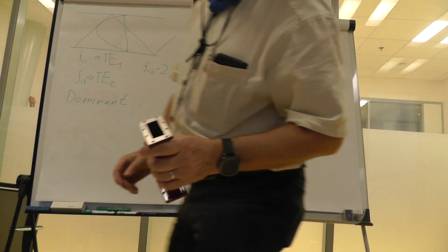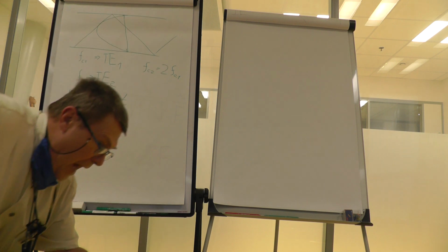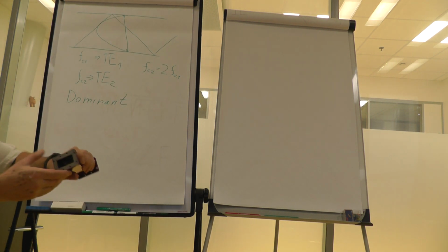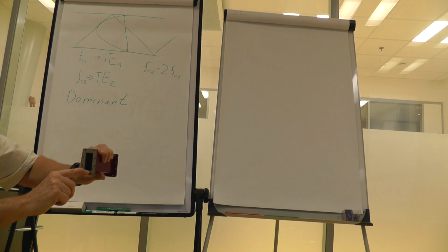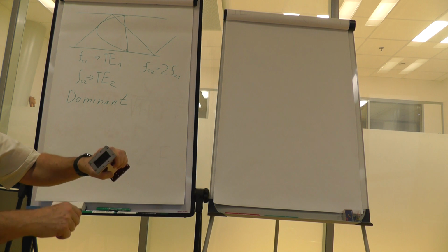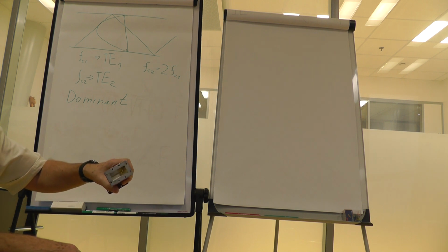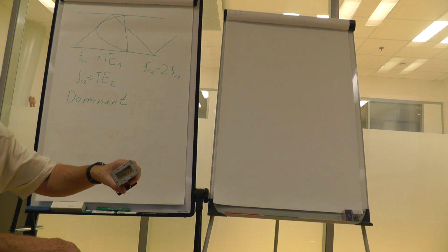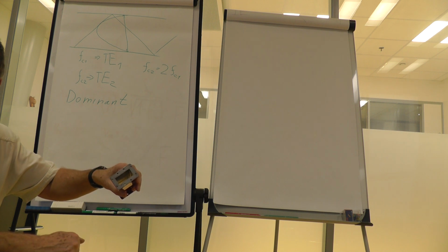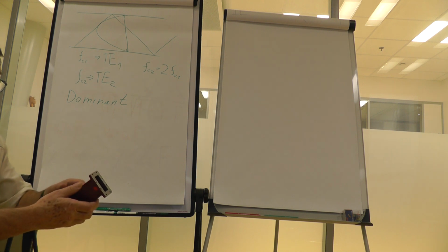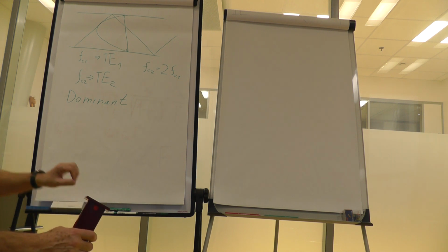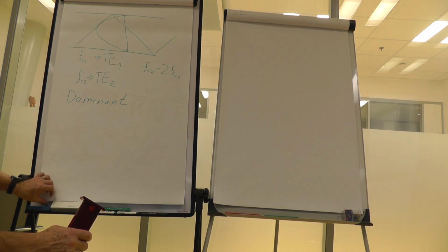So again, as to the waveguides, normally this dimension is something in between 1/2 wavelength and the full wavelength. That's because we want only one mode to propagate, and that's the basic mode TE10. Now let us switch to naming the modes and to talking about them.